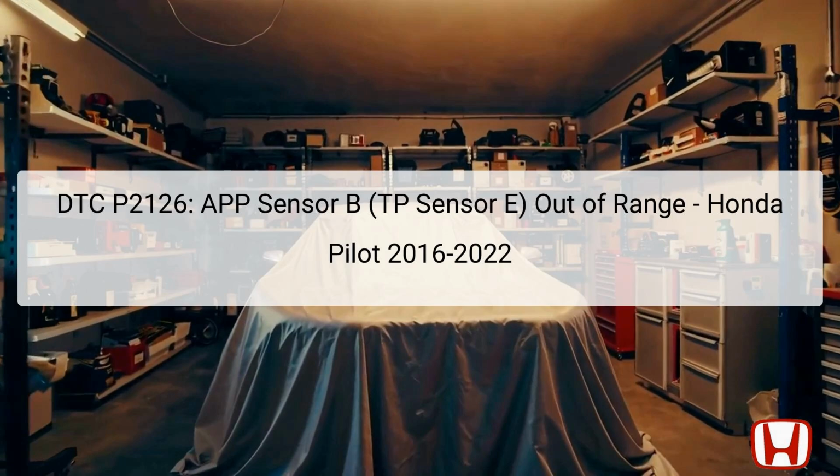The diagnostic trouble code, DTC P2126, indicates an issue with the APP sensor B, also known as TP sensor E, which is effectively a throttle position sensor used in your Honda Pilot model year 2016 to 2022. This fault arises when the signal levels from this sensor fall outside predefined thresholds.